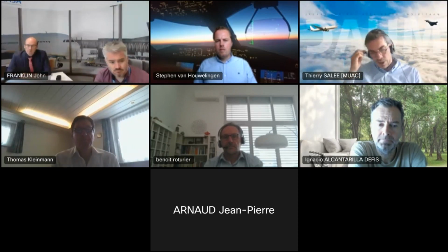Yeah, just as a last point, I also discussed with a colleague, a surveillance specialist responsible for ARTAS in our company. He told me that all the tracks or radar plots coming from the radars on the ground are timestamped as well. And if there is a difference of more than 2 seconds, the plots would be discarded by ARTAS. Okay, we have multiple coverage and so on, so we should survive it. But indeed, there is a dependency on time synchronization.